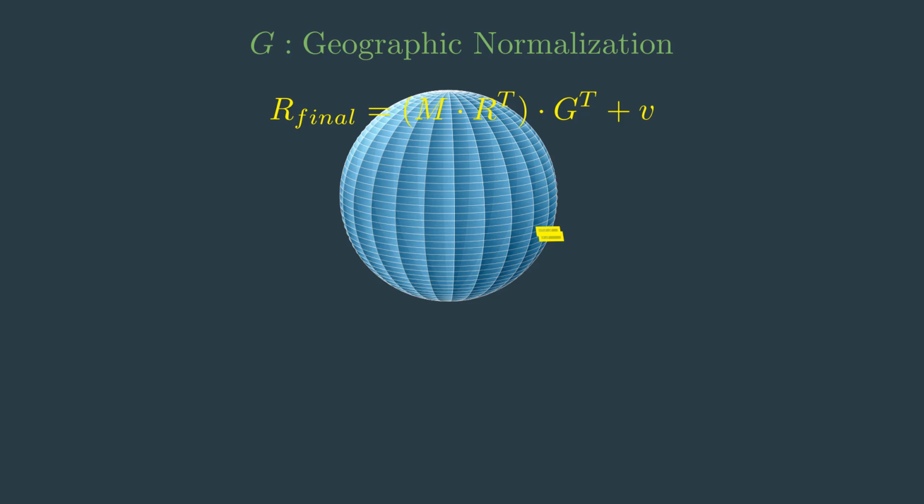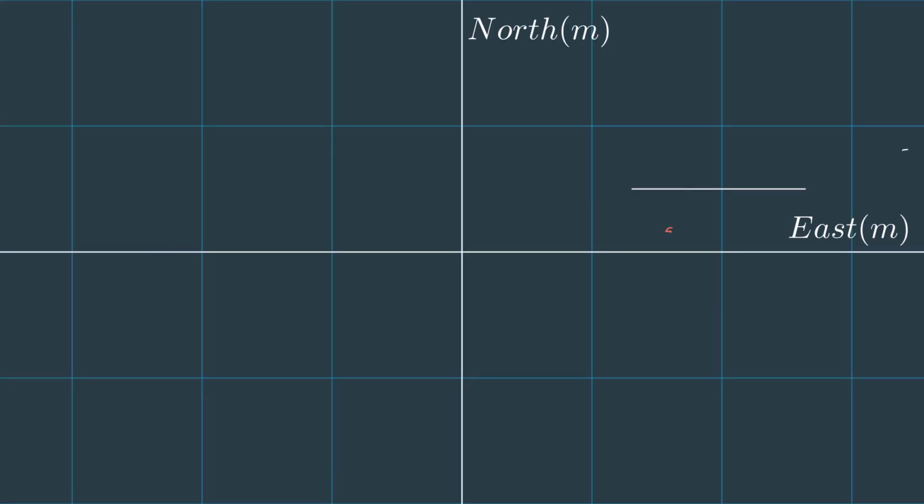But you mentioned approximations. There has to be a catch with that flat Earth playground idea, right? There is, and it's important to be aware of it. The main limitation, the fundamental simplification here, is that planar approximation. We pretended a small patch of the curved Earth was flat for calculations. And it's not perfectly flat. It's not. So doing that will introduce some amount of error. It's an inherent trade-off you make for the simplicity and speed of the calculation in that ENU system.